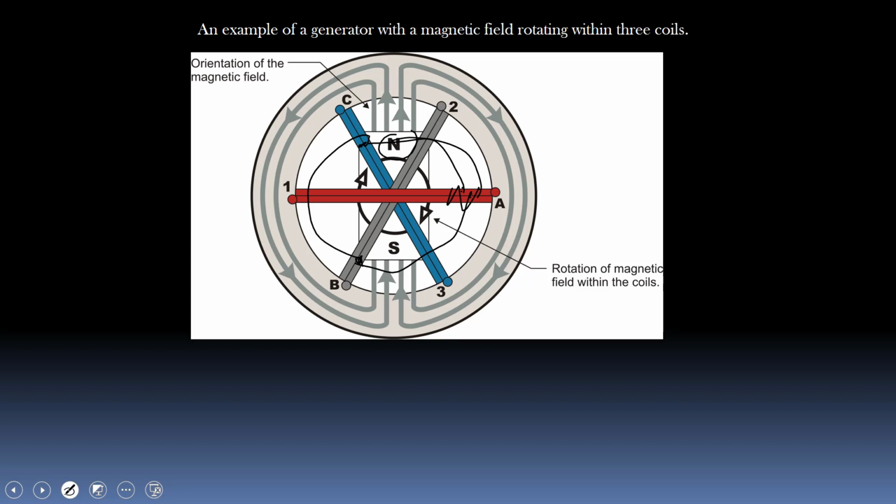What would happen? We'd be supplying, this would actually be a coil on the inside, okay, and we'd be energizing that coil with a DC voltage and controlling the current flow through that DC electromagnet, which we are rotating on the inside. So this is so we could put larger gauge wire in there, and in the stator, not rotating heavy copper wires, or instead we're going to rotate the magnetic field on the inside.